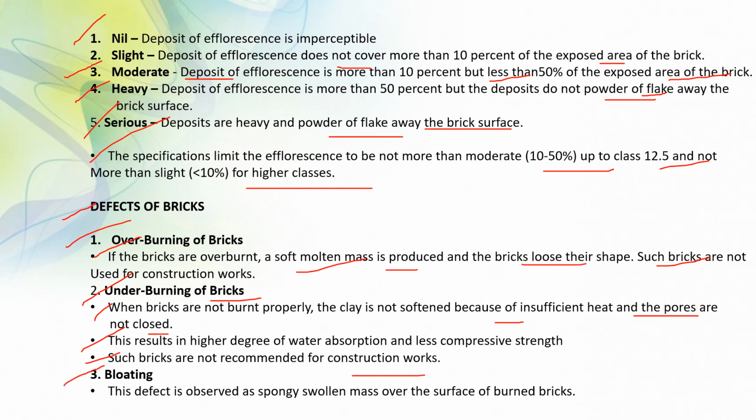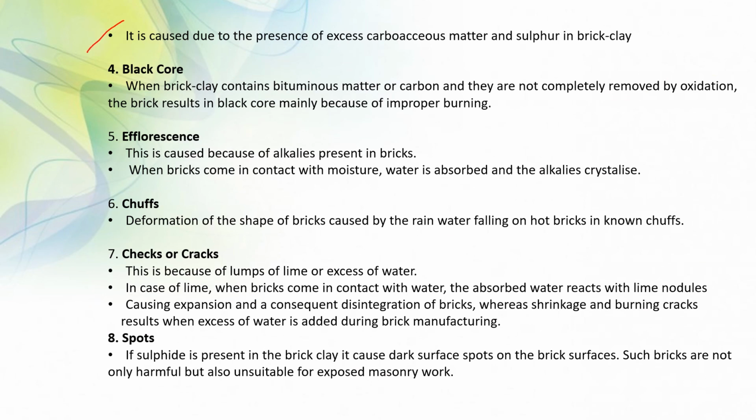Next, I will discuss bloating. This defect is observed as spongy marks over the surface of burned bricks. It is caused due to the presence of excess carbonaceous matter and sulfur in brick clay. Next, black core. When brick clay contains bituminous matter or carbon and they are not completely removed by oxidation, the result is a black core in the brick, mainly because of improper burning.